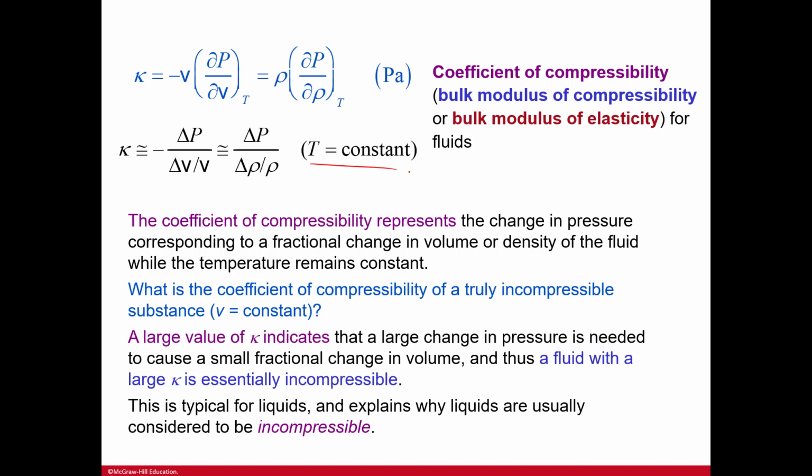So if we need to compress a fluid and we are giving it a very large amount of pressure, and therefore it has a very large K, that coefficient of compressibility is very large. And if we only get small fractional changes in volume, then it is essentially incompressible.